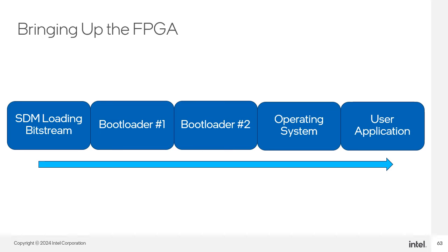After the HPS exits reset, it uses the FSBL hardware handoff file to set up the clocks, HPS dedicated IOs, and peripherals. You can create the FSBL from one of the following sources: the U-Boot Secondary Program Loader, which Intel provides the source code for on GitHub, and ARM Trusted Firmware, which is also available on GitHub.